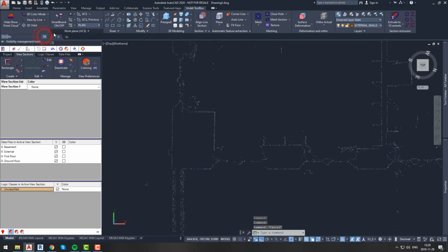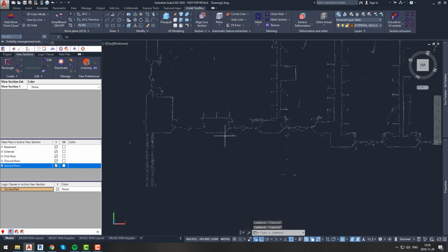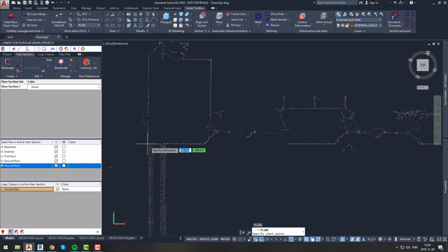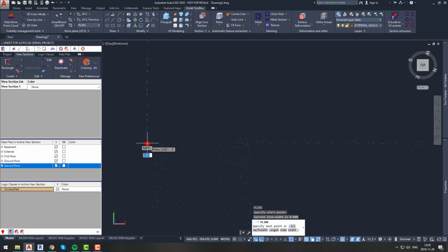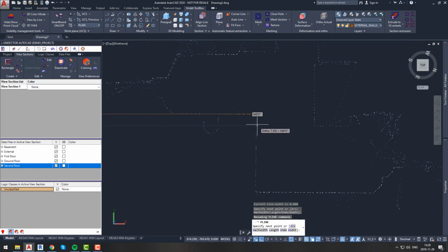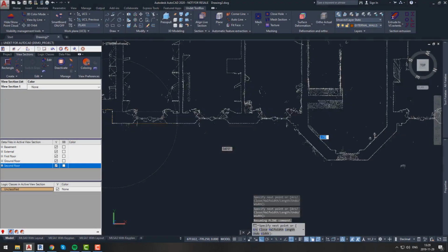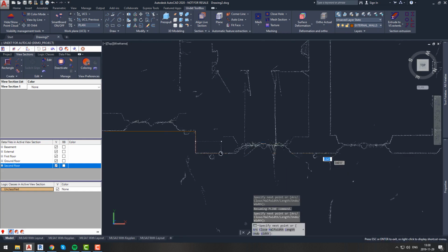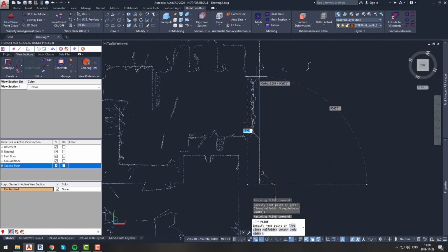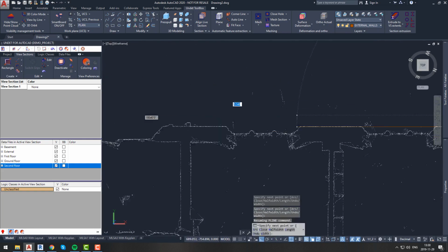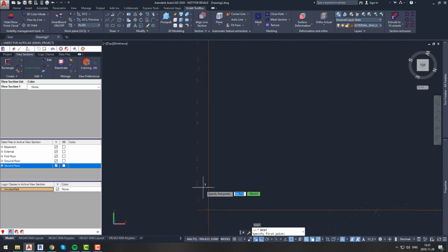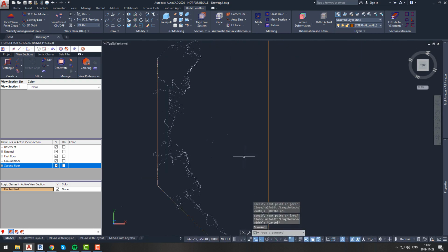Let's start drawing external walls. To do it we will select external walls layer. Simply follow building outline. It is better to draw lines that are on the same plane as one long line and then draw additional lines for walls that are not on same plane. This will help to hold on walls geometry. We recommend to use ortho mode as much as possible while drawing walls, since we created new UCS and we are drawing perpendicular walls with 30 mm tolerance.